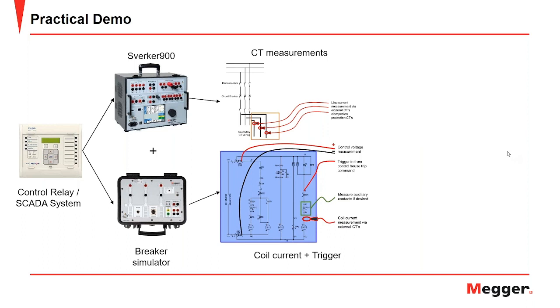Another question I'm having here is, what about motion test in brief? The motion test also can be done here. I didn't do it with the first setup, but it can be done as well, since it's related to a mechanical part. You can connect to this mechanical part as well. But here, one thing I really need to mention is that when you want to connect to a mechanism that's not been operated for a long time, you need to be careful not to touch anything and by mistake release the stored energy inside the breaker.